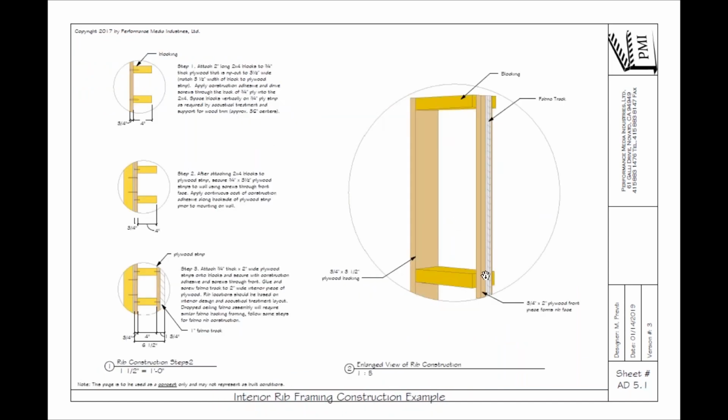The skeletal material looks like this. There's a back plane made typically out of 3/4 plywood or 1/2-inch plywood, cut to about 4 inches wide. There are kickers made out of just 2x4 material, so 3.5 inches wide. If you're building a stretch fabric wall that's 4.5 inches away from the wall because you're hiding 4-inch materials and speakers, this whole thing needs to be about 3.5 inches, because the track is 1 inch deep. That's the actual plastic bead.